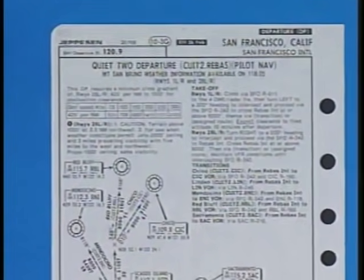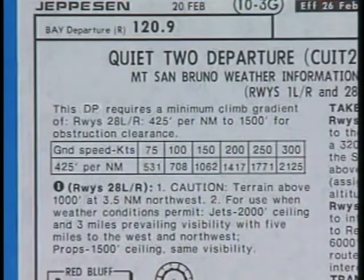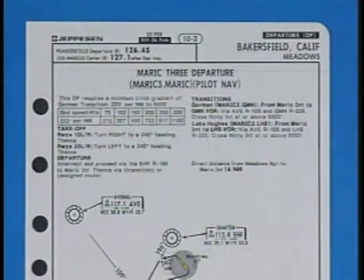Some instrument departure procedures contain specific performance requirements in order to maintain adequate obstacle clearance. You should always review the graphic instrument DP chart you're planning to use to verify that your aircraft can comply with the required performance criteria. If you cannot meet these requirements, you should request no DP on your flight plan. A graphic instrument departure procedure requires you to fly a specific route and altitude combination after takeoff.